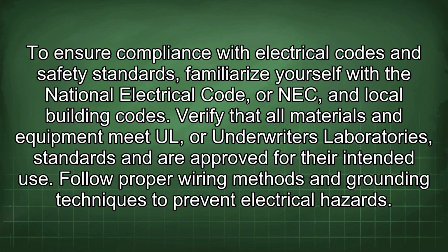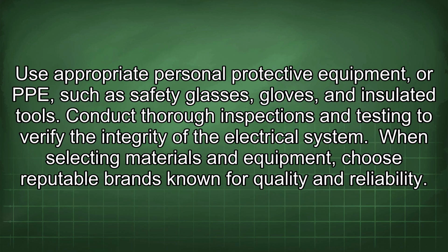Verify that all materials and equipment meet UL, or Underwriters Laboratories, standards and are approved for their intended use. Follow proper wiring methods and grounding techniques to prevent electrical hazards. Use appropriate personal protective equipment, or PPE, such as safety glasses, gloves, and insulated tools. Conduct thorough inspections and testing to verify the integrity of the electrical system.